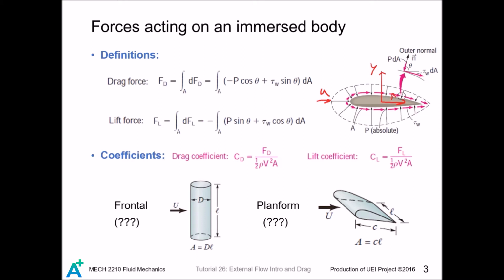As shown in the figure, the fluid force acting on the body is due to both the pressure and the shear stress, so that we can write an expression for the two components like this. For drag force, people usually call this term due to the pressure as pressure drag, and this term as the friction drag. But sometimes we don't have so much detail about the pressure and the shear stress, so we again use the empirical relations.